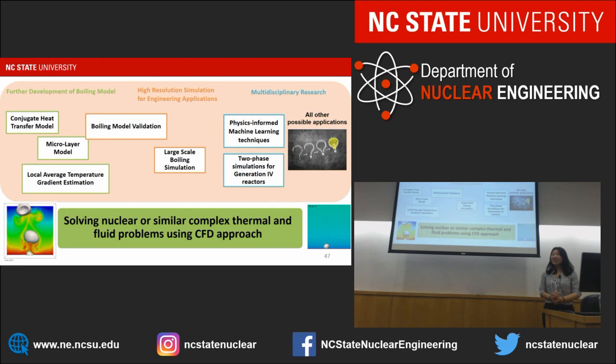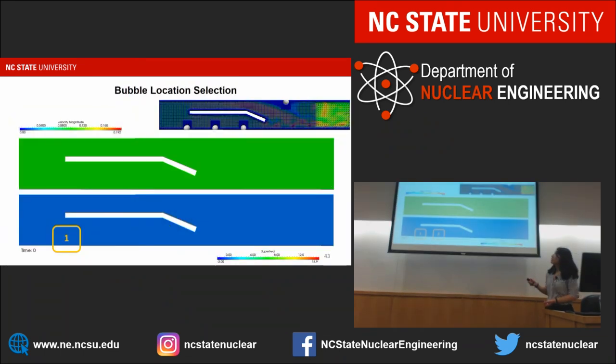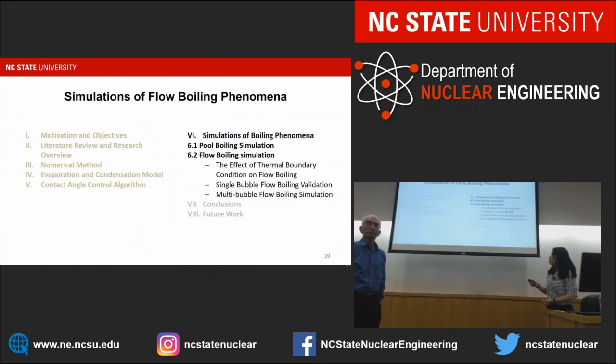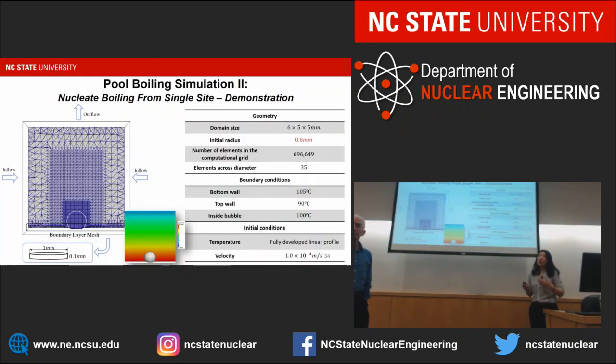Why do we need a high resolution code like PASTA that could resolve to the scale of each single bubble? Why do we need such kind of code? So just as said in the very beginning, first there's no other approach we could use to study the local phenomena in the reactor coolant channels, especially when we have all these structures like spacer grid and mixing vanes. And this approach could help us to understand what's going on under these regions.